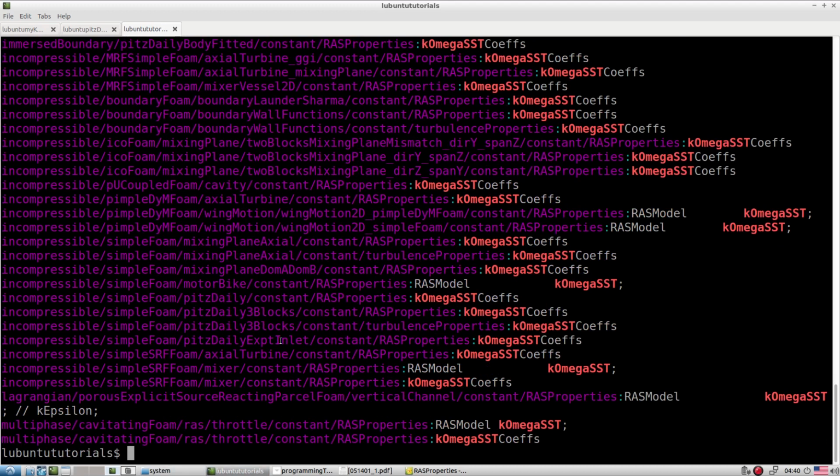So what we learned in this particular session: try to adapt the particular models from the src folder, fetch that model out, resolve the dependency, compile it, and create the template. Once the template is ready, then you have to code based on your requirement of the new turbulence model. So that is the simple thing we learned in this particular session.